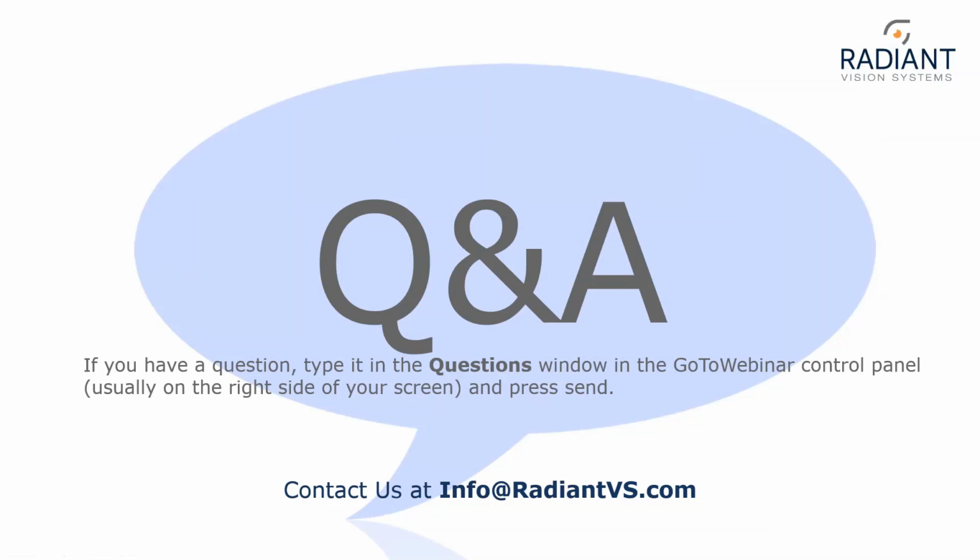The first question we have up here is, what does the registration use as a threshold to define the initial shape? Example, luminance, color, or other aspects? Yeah, that's a great question. So the software does use a luminance threshold to define the registration, or the golden sample that we talked about in the video. However, there's a lot of flexibility with that thresholding, different image processing techniques and thresholding options. So it can really be tailored to what you're really trying to do, whether that's look for defects or different options. So there's a lot of flexibility for the user there.